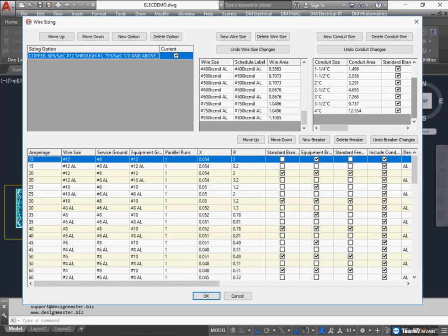And the best way to do that is to add the new size and give it a label, say half-inch conduit. And then instead of the way we like to do this, and it's kind of up to you how you want to document it, rather than saying C, you could say PVC. So that's indicating half-inch PVC conduit. And then you could also do another one, half-inch EMT. So now you can choose specifically PVC or EMT.